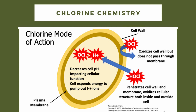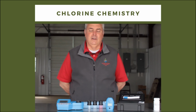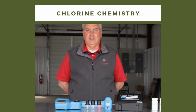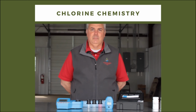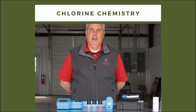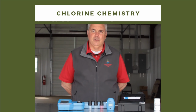Here is Chip to explain the different methods of measuring the chlorine in ag water. Chlorine has certain advantages and certain disadvantages. One of the disadvantages of chlorine is that it is most effective at pHs above 6.5. So you have to understand the pH of the water when taking into account the amount of chlorine that you're dosing.